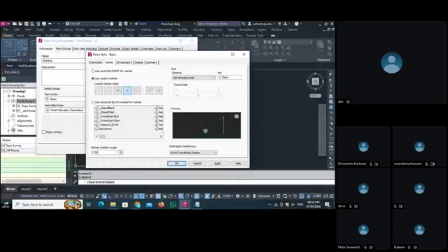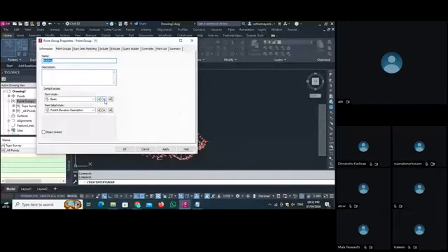If you want to select plus, or if you want to select round, or if you want to scale it, you can edit it also. But my suggestion is, whenever you edit this point style, you should copy the current style and then edit it. So your original point style has no changes, and you can easily use your own point style, which is editable.